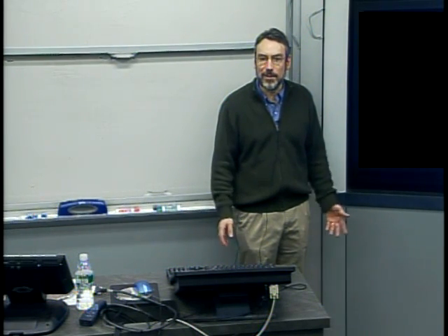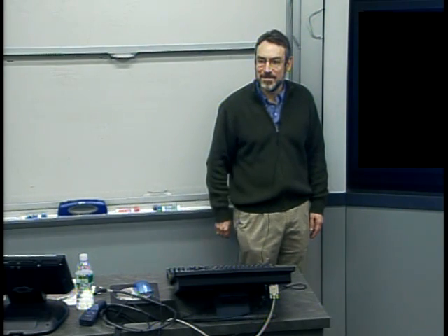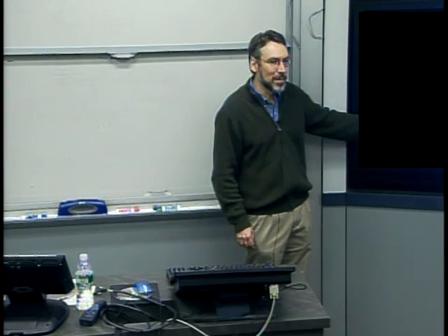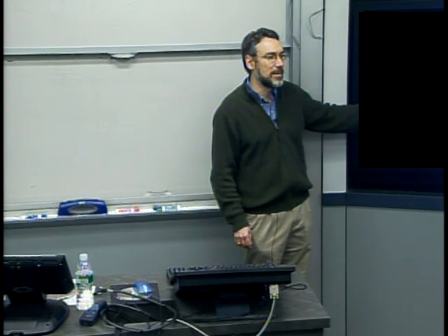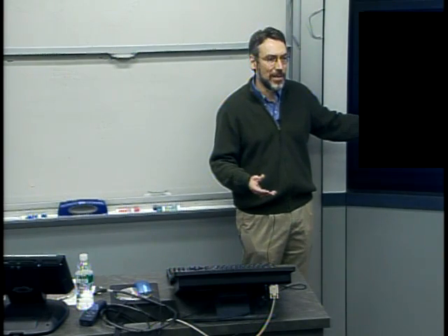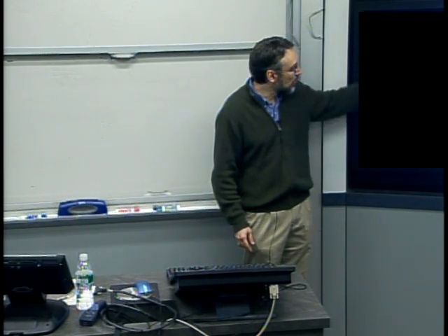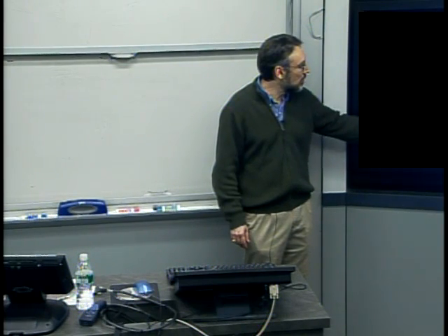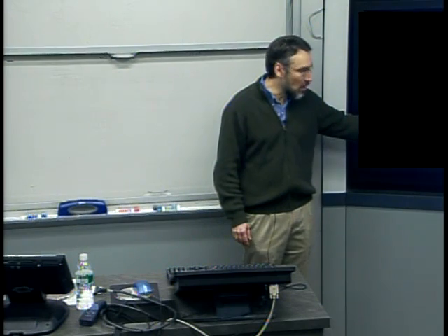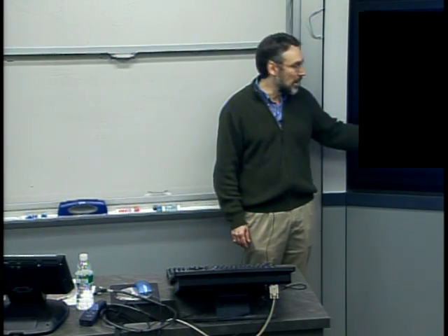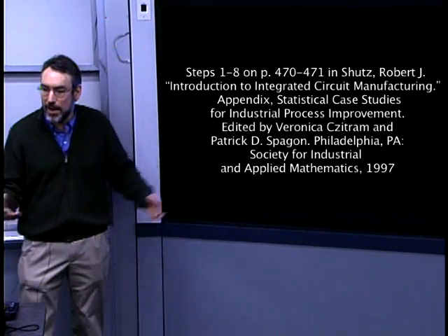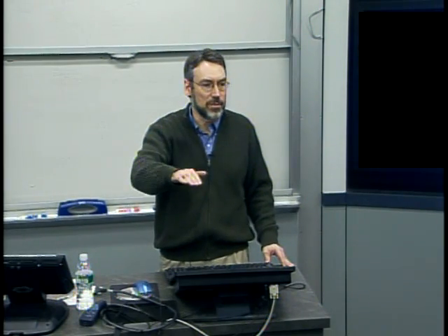So what do you think they really do? Etch all the way through, then grow another layer? That's exactly right. We can controllably etch all the way through using ideas of etch selectivity. The same idea I mentioned, we can choose an etch chemistry that allows us to etch silicon dioxide and not etch photoresist. We can also use one to etch silicon dioxide but not etch silicon. You can have very good selectivity so that one can stop controllably on the surface of the silicon.